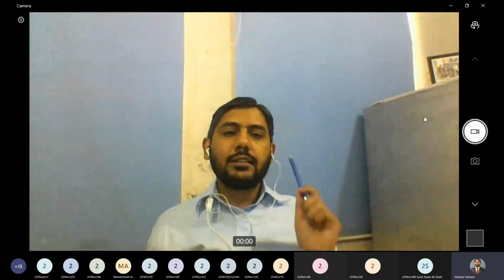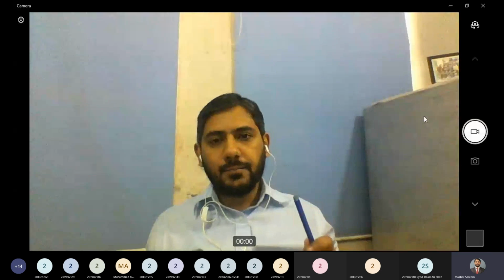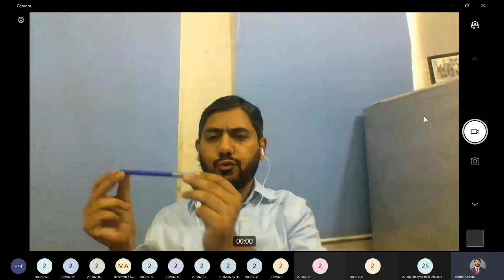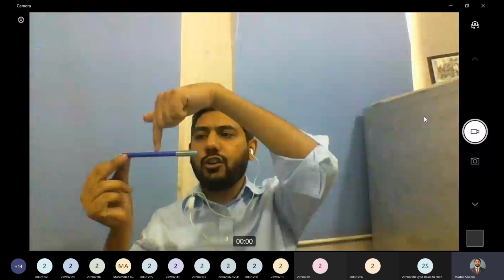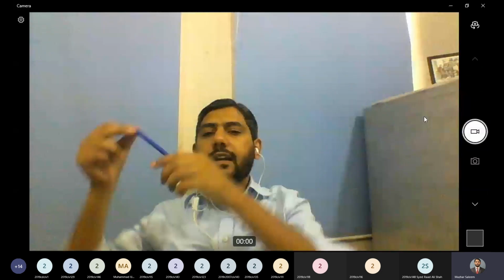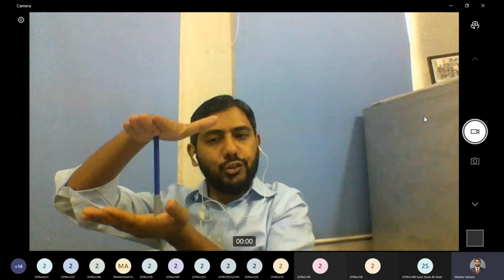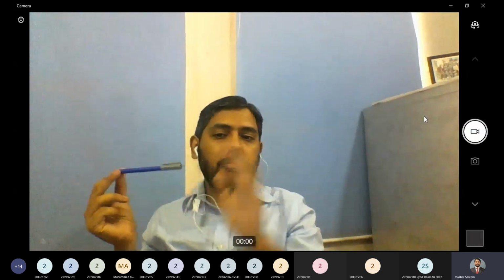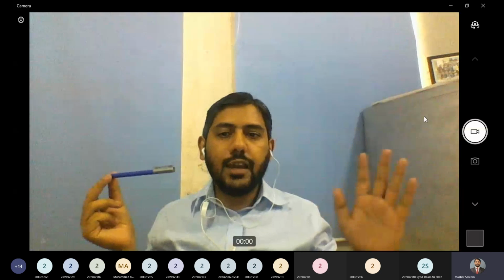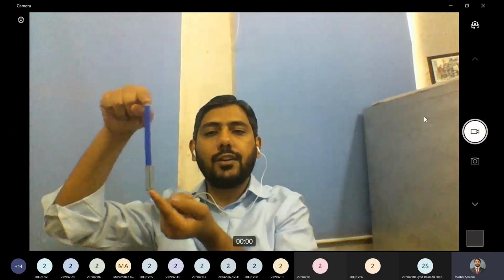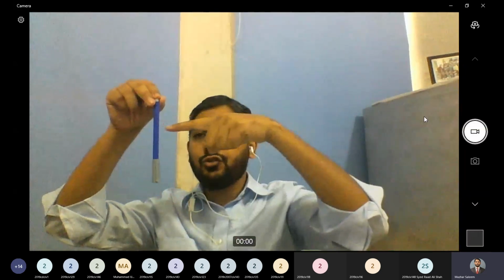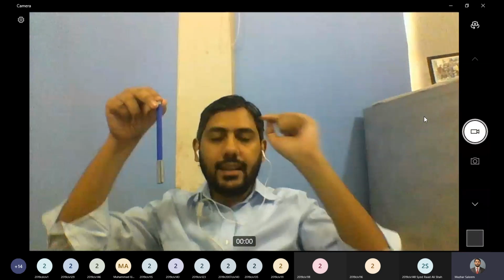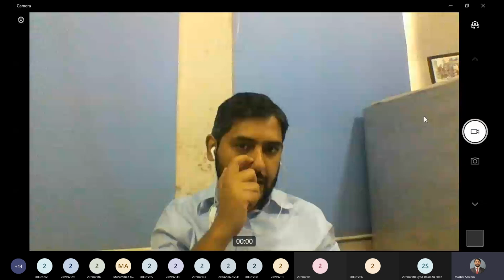For civil engineers, the behavior of the member is important. If a member is subjected to transverse load, meaning perpendicular to the longitudinal axis, it is a beam. If it is subjected to compressive load, it is a column. Most of the time, columns are vertical and beams are horizontal, but this is not an absolute truth. We may have vertical beams. If we have a vertical member and it has transverse loading, that member will be analyzed and designed as a beam. It will not be treated as a column.